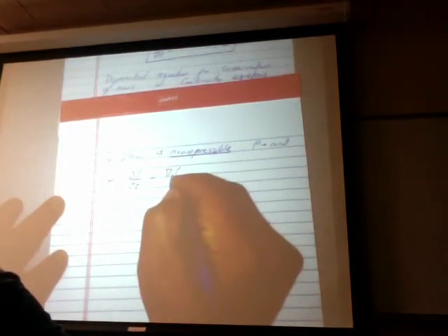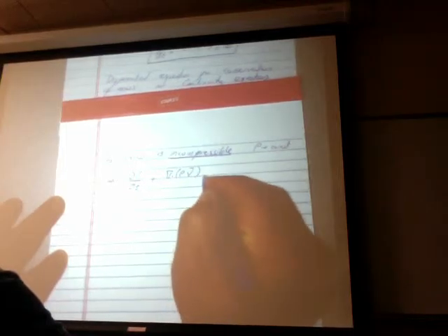turns out to be, so this one goes to 0, right? If the density is a constant, it doesn't change as a function of time. And because this is a constant, it can actually be taken out of there. And then that leads to the divergence of the velocity being equal to 0. And that's where it comes from.